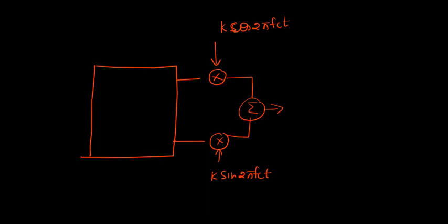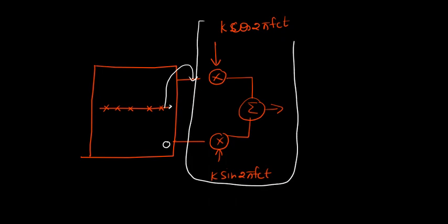So, in ASK what would you do? You will use some mapping and these values will go here and here always 0 will be there. Yes or no? Yes. So, this will not change, this will be fixed. This is called the up conversion block. This up converts your frequencies. Then there is the bit to constellation mapper.